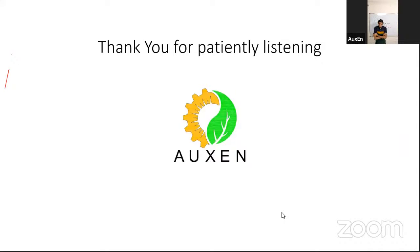Then Mr. Mustafa is saying, two mid-landing stairs included or dog-legged? That will depend again on the architectural plan that we have. Generally, in residential buildings, you will see a dog-legged staircase. In commercial buildings where we have a greater floor height, you may come across a two mid-landing staircase. So whatever plan we take up, we will consider that staircase. Maybe in the commercial plan, we can take up the two mid-landing staircase. In the residential plan, we will take up the dog-legged approach.